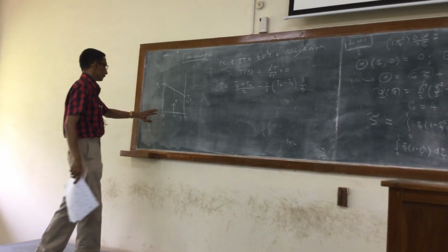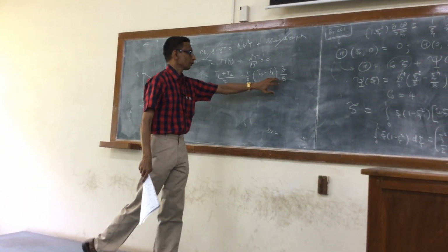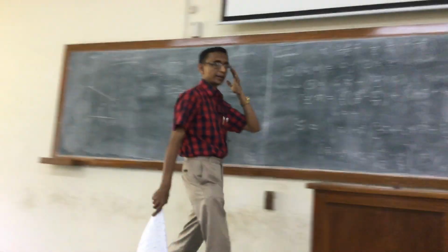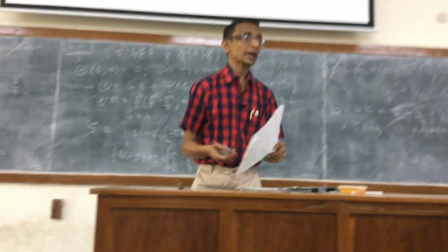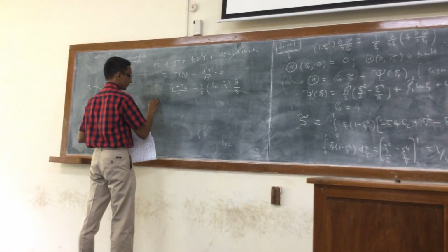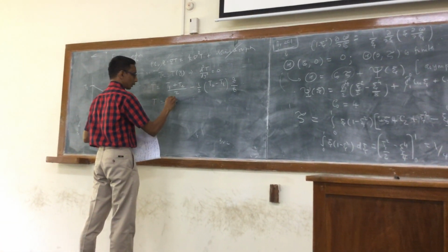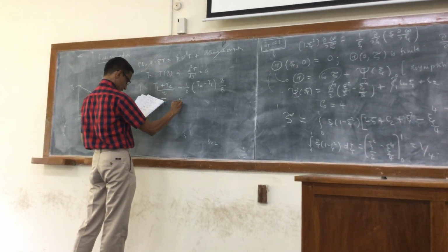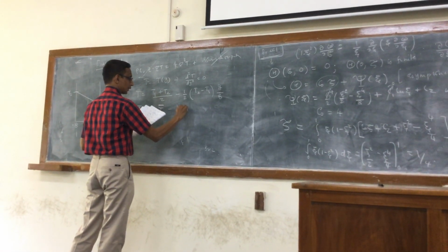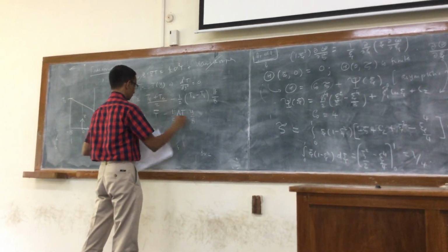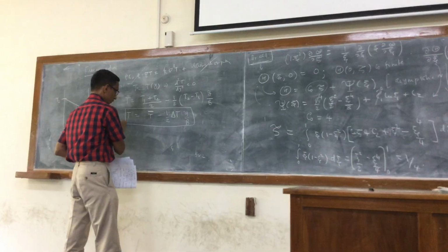You can clearly see that when y equals b you should get T1, and when y equals minus b you should get T2. That will satisfy the boundary condition. He then defines this as T bar, the average temperature (T1 plus T2)/2, minus half delta T, the difference in temperature, times y over b. This is the temperature profile.